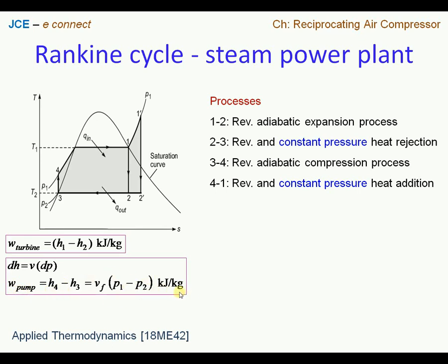per kg basis. Therefore we have a small letter w, specific work input by pump. Similarly for turbine also we have small w because it is on per kg basis. Therefore one can call this a specific work done by turbine. Now moving further, let us look at the heat quantities. Heat that is added into the system on per kg basis, therefore we have specific heat input, which is given as H1 minus H4, straightforward.